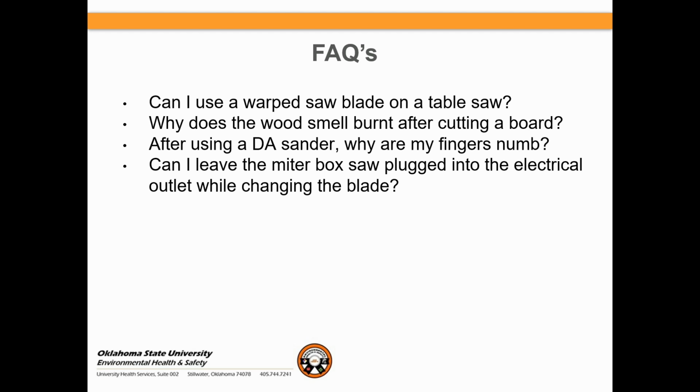as far as after using a DA sander, why are my fingers numb? Okay. One thing about the DA sanders that I did not mention, which is very important, is they will cause your hands to go numb. A lot of times gentlemen wake up in the middle of the night shaking their hands, going, what has just happened to me? What's going on? Well, here's the thing.